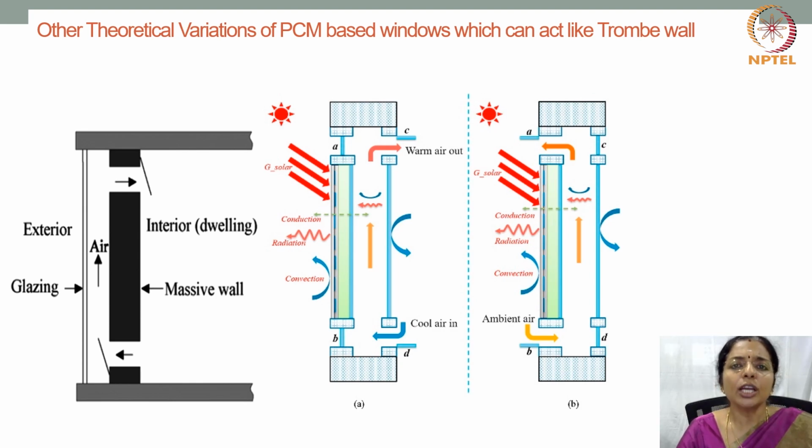The combination of trombe wall and solar photovoltaic panel is a viable combination to generate electricity and supply heat simultaneously. The thermal performance of a trombe wall depends primarily on its mass, since it stores sensible heat. More mass means more capacity to store solar energy and less temperature fluctuations.